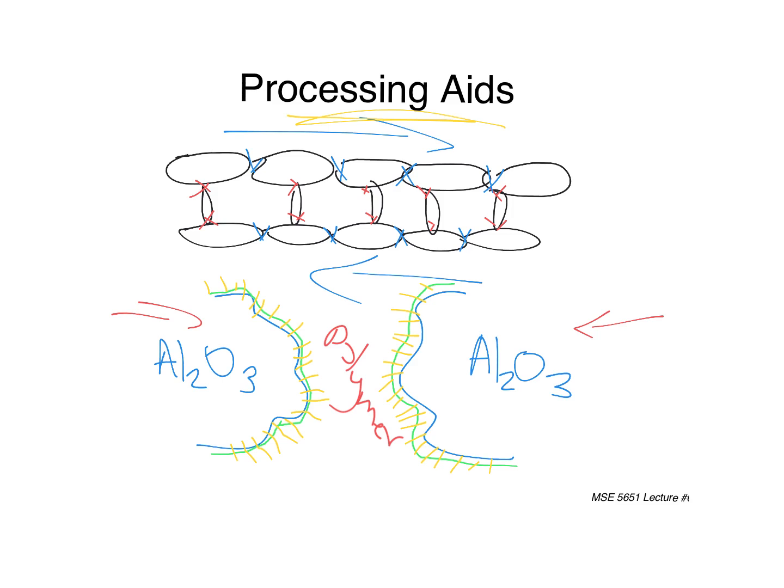All right. Yes? So do you still need energy to break them apart, but just not as much? Nowhere near as much. Yeah, it's much, much easier. We also don't, because they're not big hard agglomerates, the consequences of that are much more minor. So if I have a hard agglomerate, it's a bunch of particles all stuck together, that's likely to form a defect. That's the issue. All right. These soft agglomerates, when they do form, they can be easily deformed. They form more coherent structures, and the defects involved are much, much smaller. Okay. But at a minimum, we start with the processing aids, and then we ideally get them to go into the polymer as well.